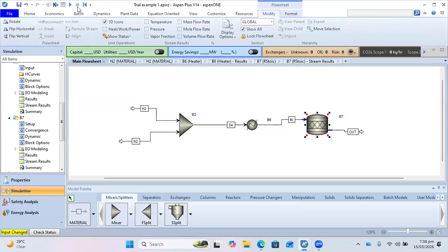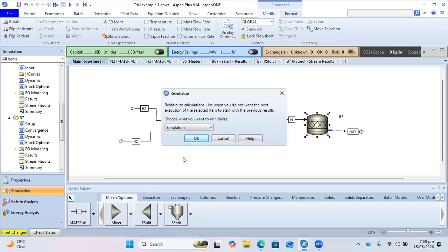So if we have all of these things down, we can now continue from there. So I'll just reset it and then I would run the simulation one more time. And please, that's also another very important part of our Aspen simulation. Sometimes when you run a simulation, especially if it's a very large simulation, Aspen stores some of the data. So it might keep some values, right? If you want to rerun the whole simulation, maybe you made a very significant change, it's advisable that you reset it before you run again. If the change is not so significant, if it doesn't have maybe a lot of recycle loops or it's not a very complex plant, you can just run it normally. But then one of the things I really like to do is to always reset before I run.